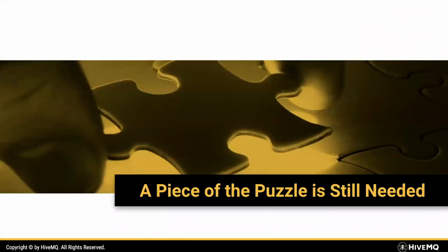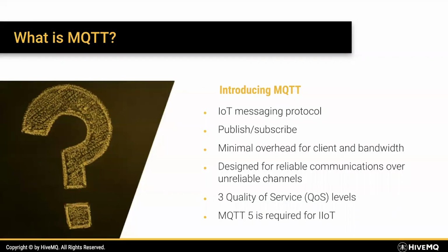But as I said, it's not only about Kafka. Especially on the shop floor, you see a lot of MQTT nowadays, and this is for a reason. MQTT is an IoT messaging protocol, and it was designed in 1999 for SCADA systems, actually, for connecting SCADA systems over the internet. It was invented by Arlen Nipper and Andy Stanford-Clark, who are still evangelizing the technology nowadays. And it's by far the most popular IoT messaging protocol, and now it's taking over the industrial Internet of Things.